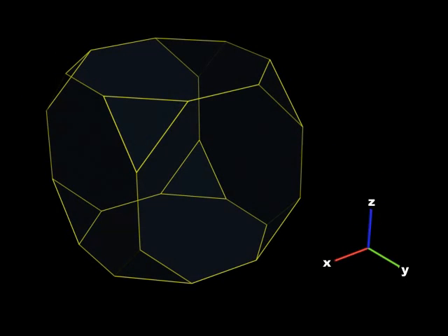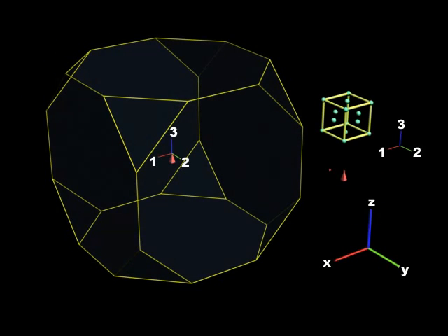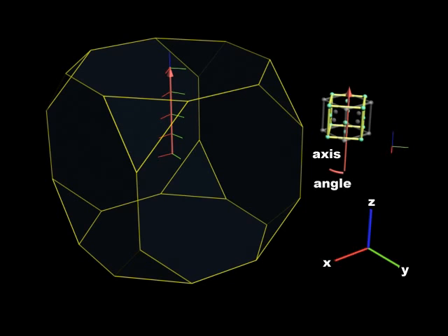Rotating around a single axial vector shows the symmetry of the FCC unit cell. For a cubic crystal, a 45-degree rotation about a 100 axis is equivalent to one of -45 degrees. We start with the crystal and sample axes aligned and rotate it about the sample Z axis, which is the crystal 100 axis. When the vector reaches the box boundary after a positive 45-degree rotation, we reposition it to its symmetrically equivalent point at -45 degrees of rotation.